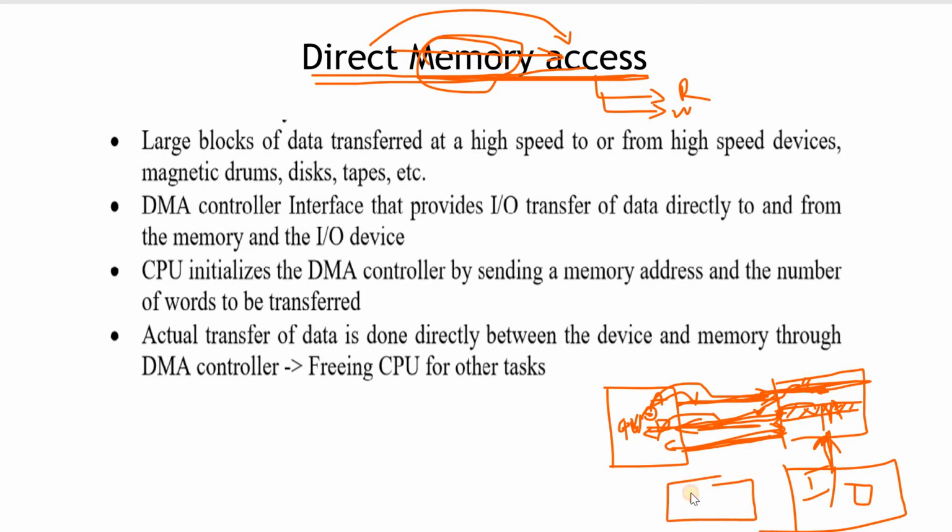The device is called a DMA controller. This is very important. That means the DMA controller. The IO device requests one more controller device, that is, a DMA controller: please handle this operation. With the help of this DMA controller, without involvement of the CPU, the DMA controller directly accesses IO devices to memory, so that the speed of operation is very high.